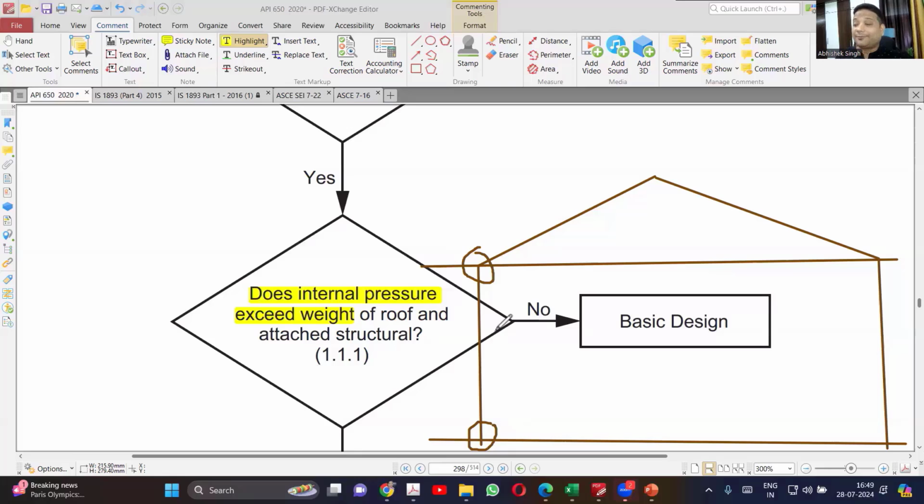But in the case of a fire, or pressure suddenly rising because the vent you provided is blocked or the vent capacity is not sufficient, the tank, if having pressure, will try to blow. If it is blowing, it should blow from here, not from here.